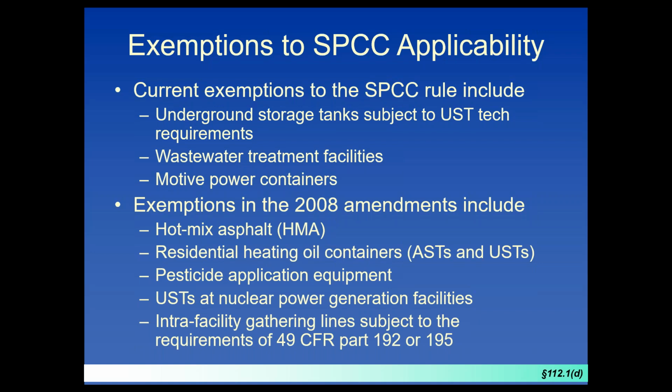This is really important for you guys because I know some of you may be wastewater treatment operators. And please, I have gotten this question quite a bit. This is not a facility-wide exemption. So what we don't regulate is the flow-through process, like, going back to my inspection days in Virginia, the headworks, the clarifiers, all the way to the digesters and active aerobic, I'm probably making a fool of myself now, to where you have your discharge. That is all something that we don't touch upon, because theoretically there could be oil in that. That's under an NPDES permit.